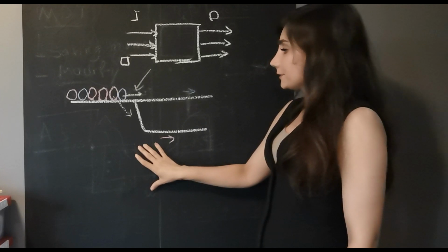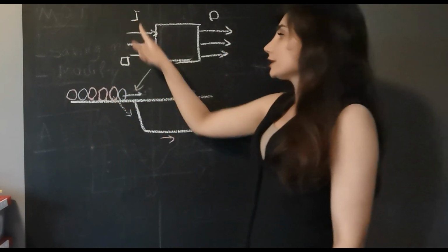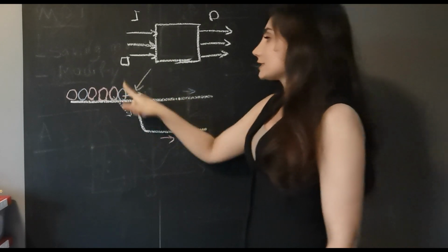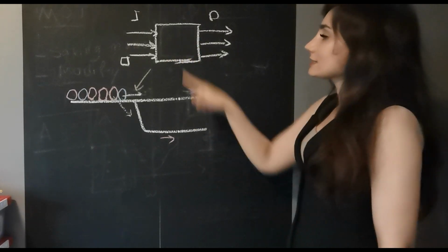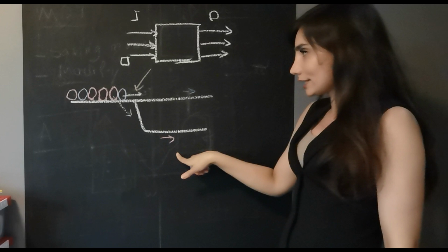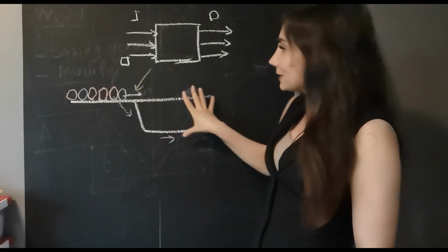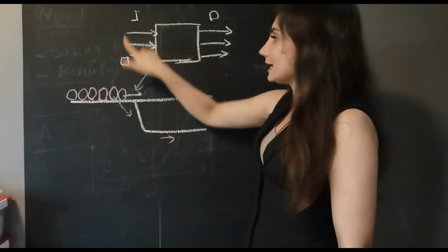And in this case that we are talking about, this sensor that senses the color of the ball is going to be our input, and it will sense if it is blue or if it is pink. And then the program here is, if it was blue, let it go. If it was pink, push it out of the way. If you want to translate what's happening here into this logic, we have a sensor, which is an input here.